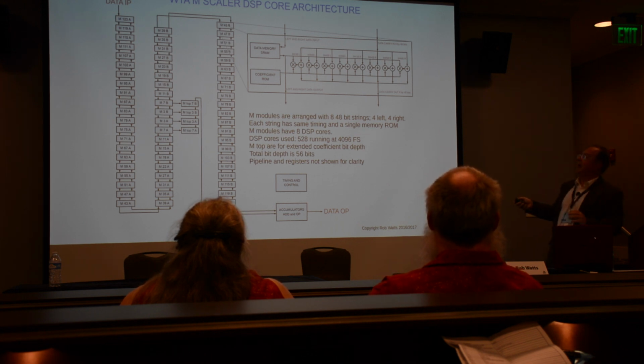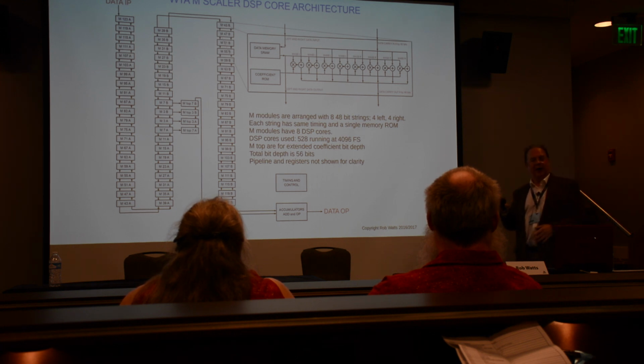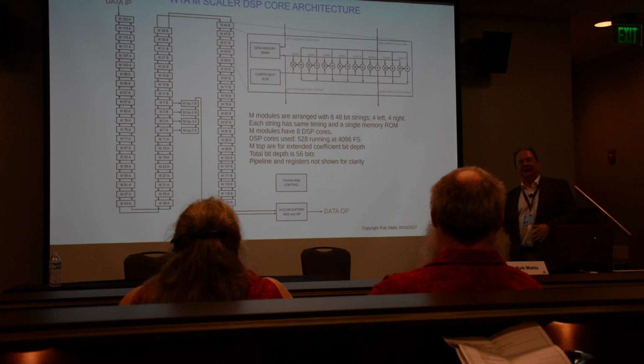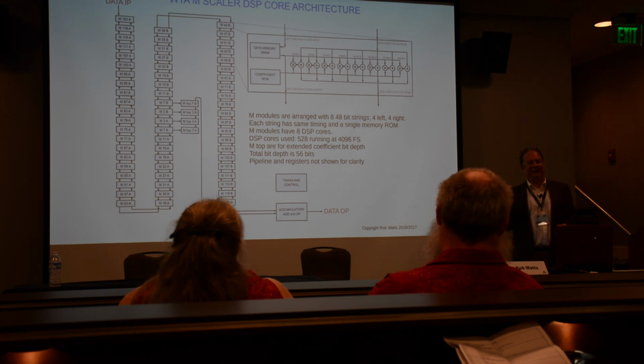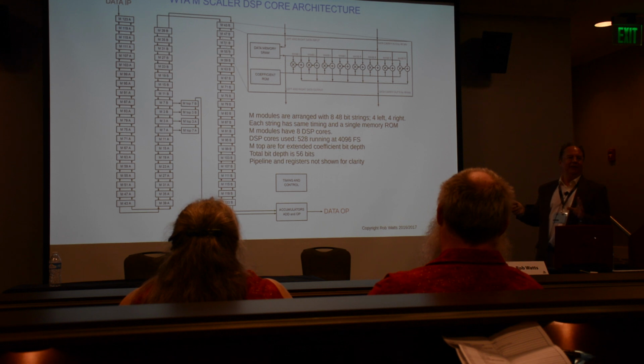Normally I would have 1 DSP core with 1 memory block. So doing it this way made the memory much more efficient. There's another benefit in running it this way. It was much easier to code. And that's something, I see you're smiling, that's really crucial when you're doing a big project. The efficiency of coding is very important. This made it a lot easier to code because I've reduced the coding size by a factor of 8, because it was 8 types of blocks.